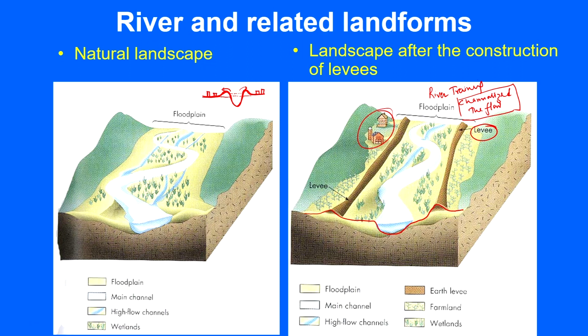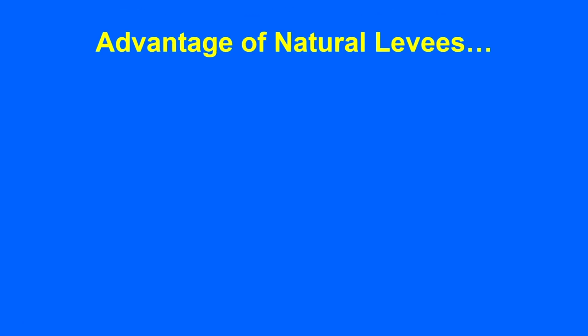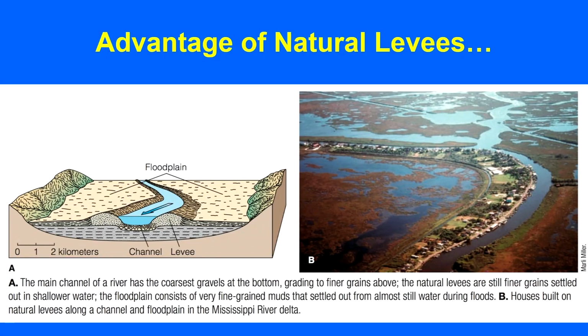So, what we are expecting from you is that when you are given some exercise to map the geomorphic features, you can talk about all this. Okay. So, another advantage of natural levees: unless and until it has been breached, this area will get flooded, but mostly you will see that these areas are protected. So, you can see now the clear-cut cross-section profile of the artificial levees which has been constructed, and which shows that the channel has been trained to flow through this pathway.